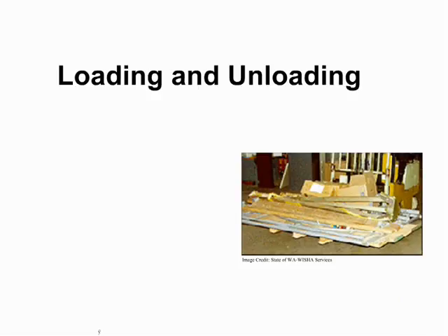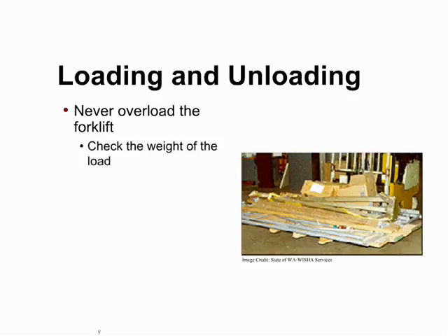Loading and unloading a forklift must always be done safely. Never overload the forklift beyond its rated capacity. Check the capacity on the nameplate and know how much your load weighs. It does not help to try to increase the capacity by adding weight to the rear of the forklift. In fact, this is very dangerous.